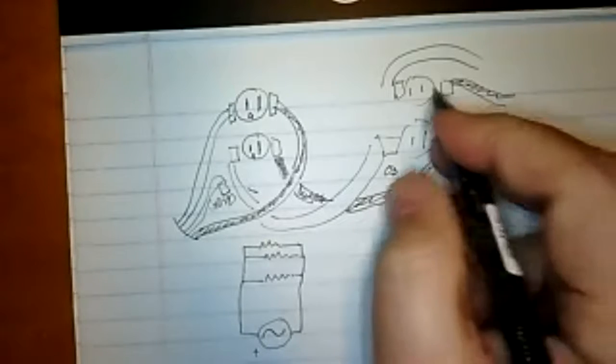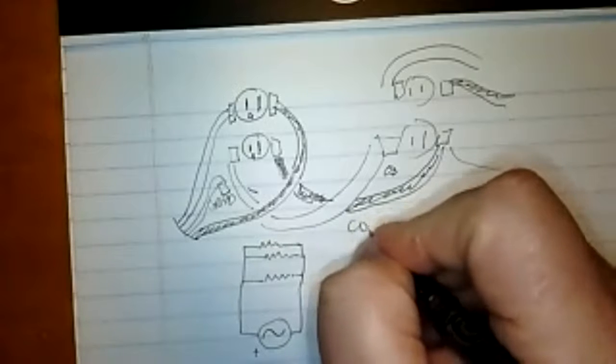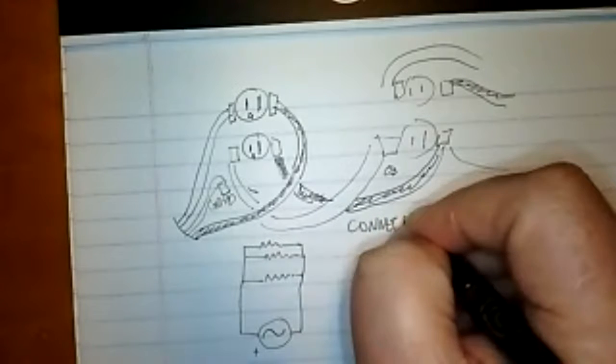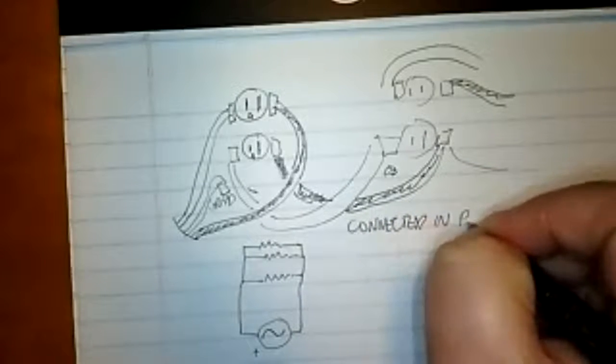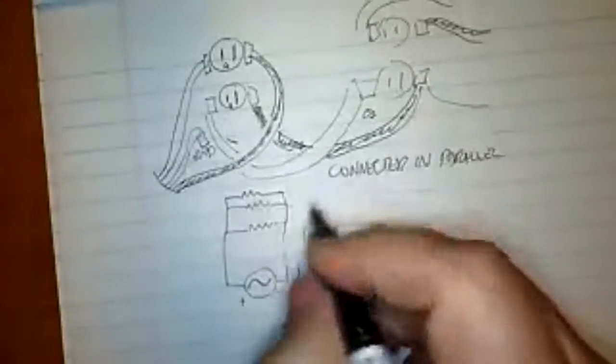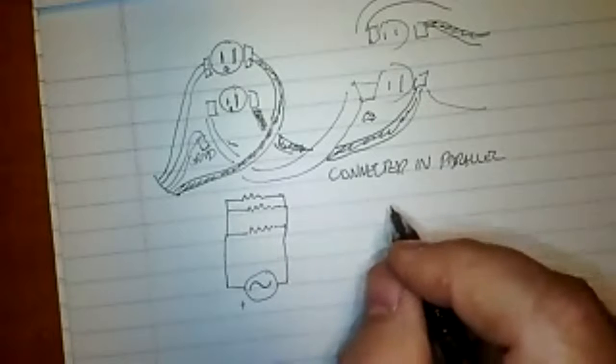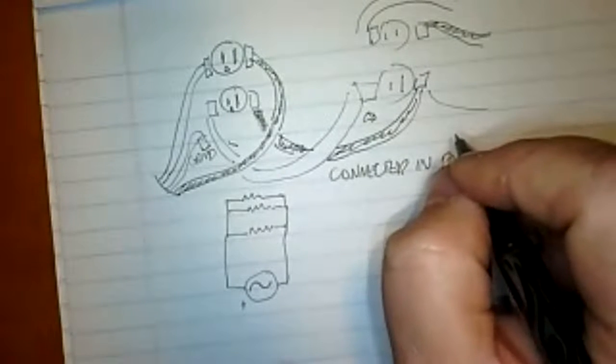So what you're seeing is that, in fact, light receptacles are connected in parallel. So they're all connected in parallel. And that's good, because if they were in series and one would burn out, then all of them would burn out like old Christmas tree lights. Okay. That also means that everything has the same voltage. Everything's at that 115, 120 volts.